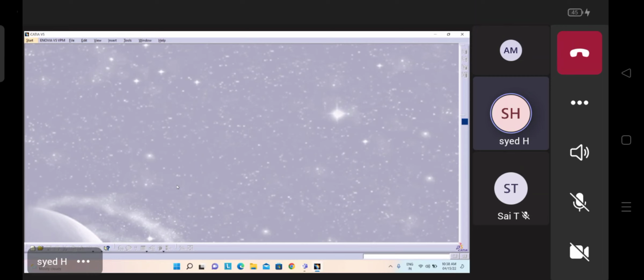So top-down approach in the sense, in that approach we will directly enter into the assembly first. From there onwards we will create a component by entering into the part level from there only. We are not closing our assembly workbench. We are in assembly level only. We will enter into the part level from there only.